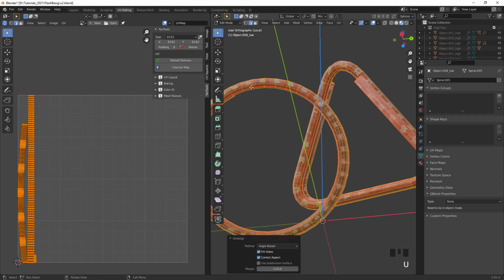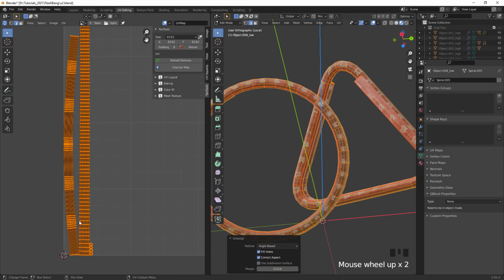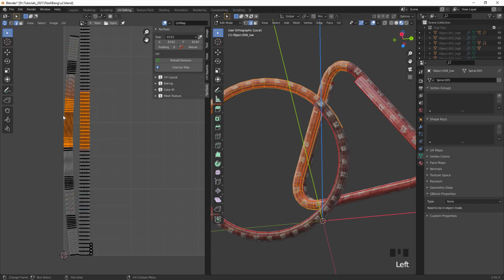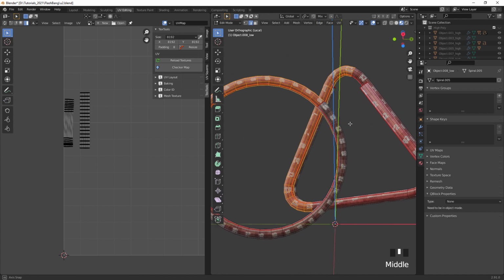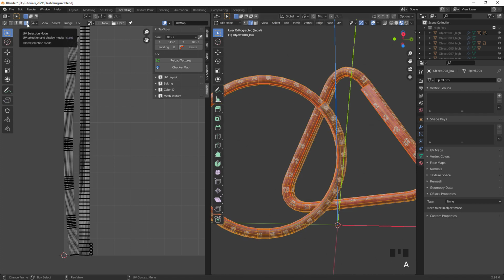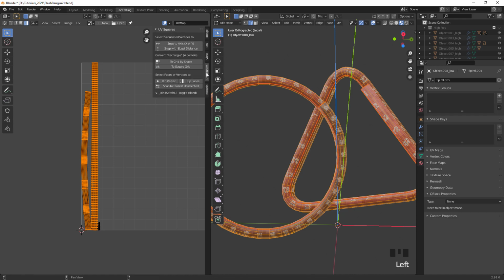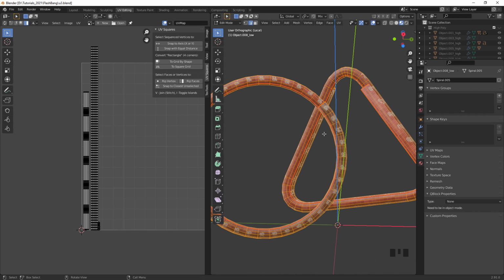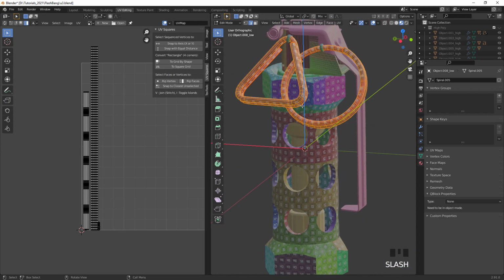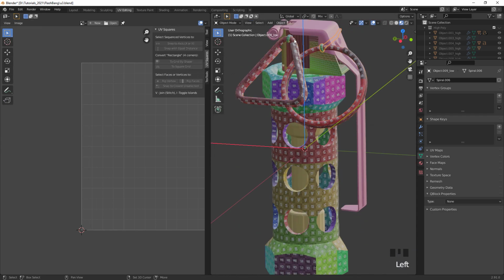And now let's just unwrap everything. And now we can make perfect use here. Let me just get out of UV Sync, because in UV Sync we can select in element mode. UV selection to select these two. And then perfect use case for snap with equal distance. You can see how this UV squares is really doing a fantastic job.